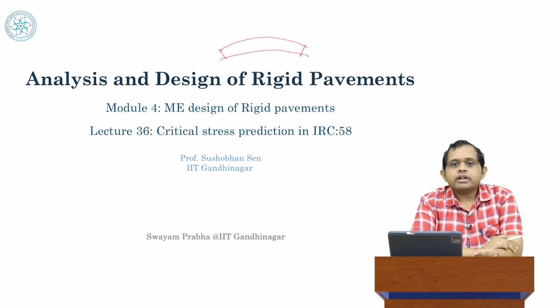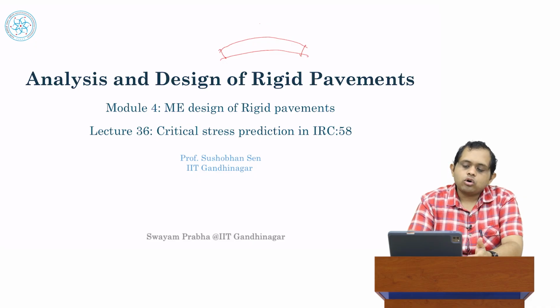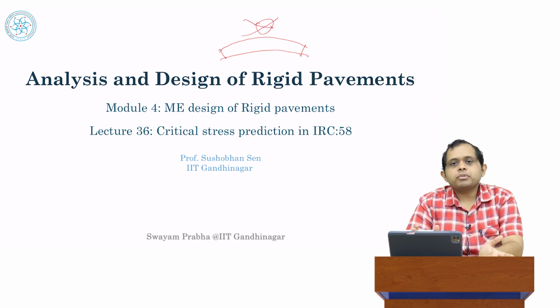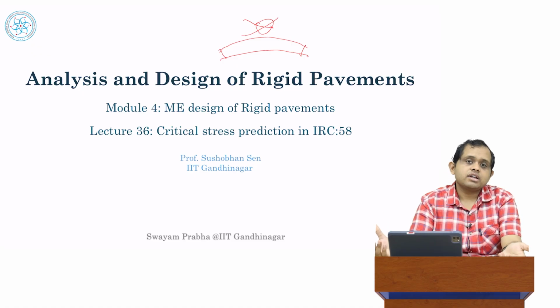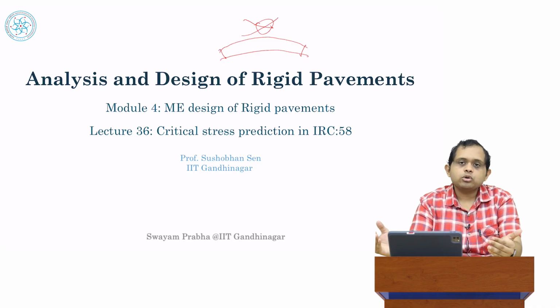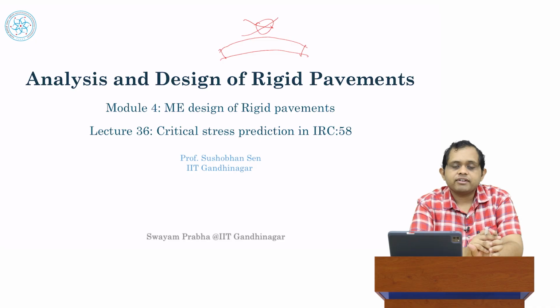On its own, without any sort of external restraint, the restraint being, for example, a load or self-weight, on its own, no stress is developed. So without any external load, this shape that the pavement tends to take, it will take, and therefore it's free to assume this shape and there is no stress. Stresses are only developed when there's something to prevent or some kind of restriction to this type of strain which is being developed.